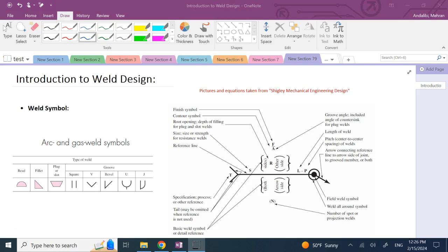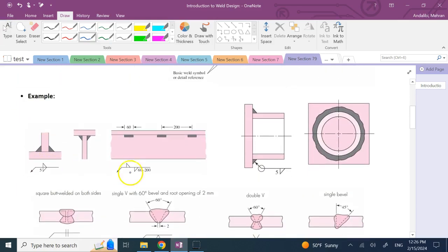I talked about this in one of my technical drawing videos and drawing in CATIA. But here I want to remind you that the symbol for welding, if you see it anywhere, is like this. It's basically a leader arrow, and it can have this tail at the end, and there are some writings above and below it, either both of them or one of them. And at this corner here, you can have these circles. So this is the overall appearance for a weld symbol. In a drafting, you might see something like that. If you see that, that is a weld symbol.